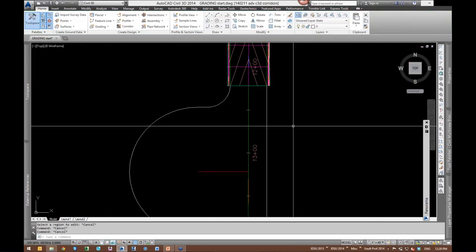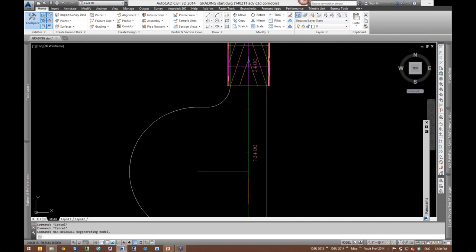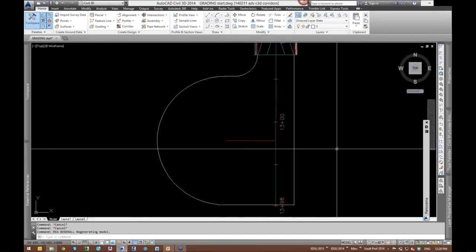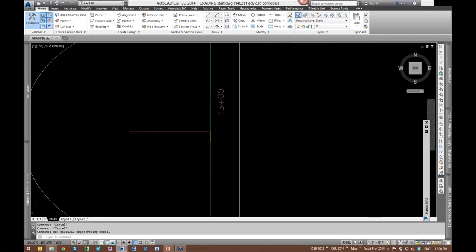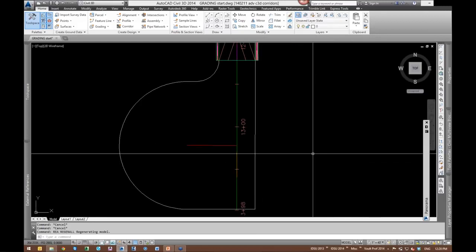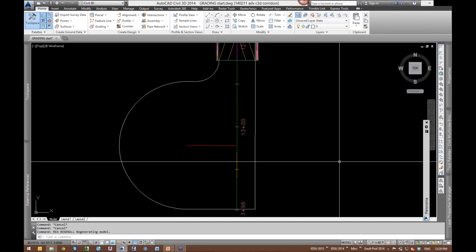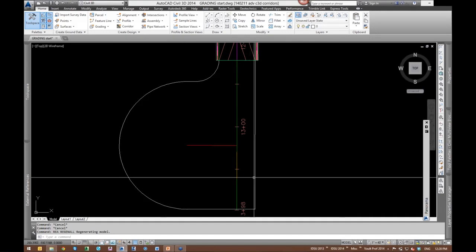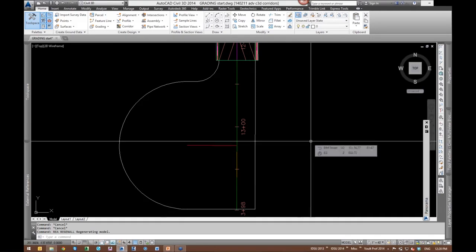So coming down here, we're going to use a similar approach, but things are a little bit more complicated. It's not just simple use of the auxiliary corridor, but it's also using targets in a smart way and modeling this in a smart way. Now, the way this looks, every cul-de-sac, almost every one is different. The radius is different. You don't have a 90-degree here. Different strategies for different projects. Just in this afternoon, though, we've got time to show you one strategy for one type of cul-de-sac.